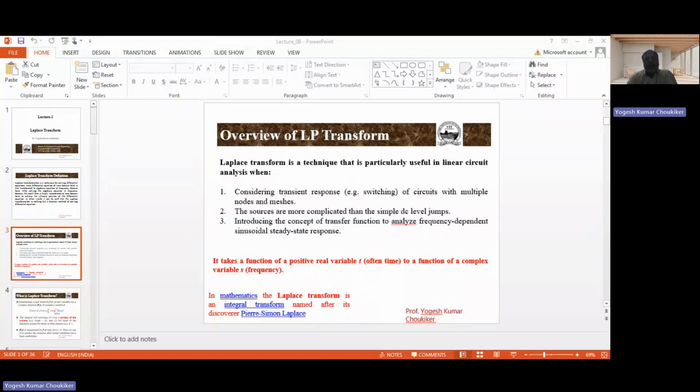Now our work will start from the lumped elements, which are the resistor, inductor, and capacitor. If we take the resistor in the S domain, first of all we have to recall the IV relation in the time domain. The IV relation in the time domain is v of t equal to R multiplied by i of t.